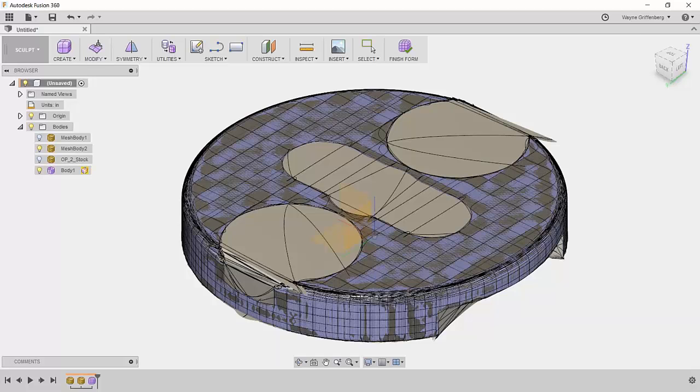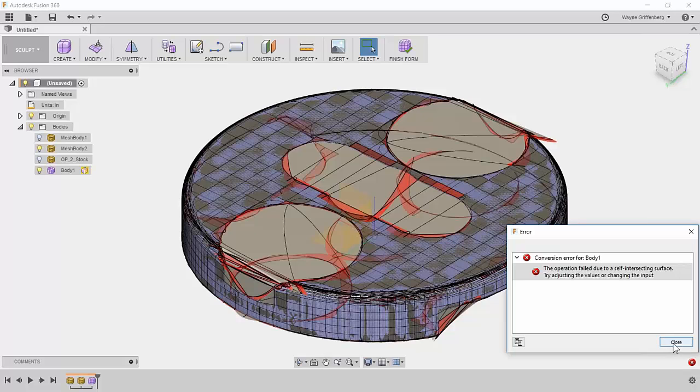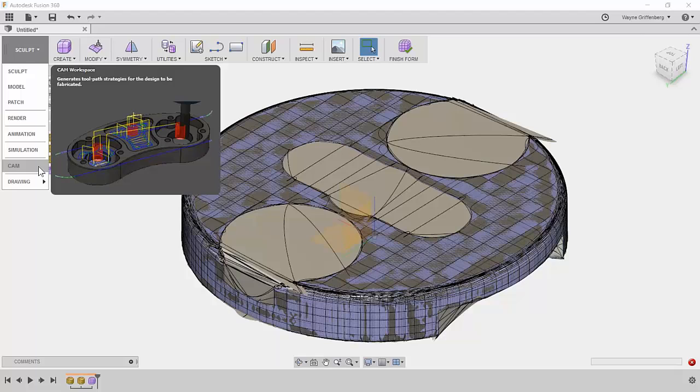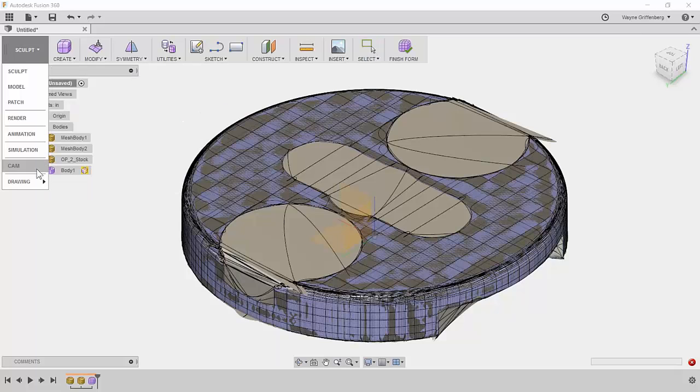I also wanted to draw attention, Wayne, if you can go back to CAM, I don't know how many people picked up on it, but a great workflow you used in machining the backside of your part, where he copied and pasted his setup and then just made a couple very small changes to toolpath the whole backside of the part. If you're not doing things like that and reusing the knowledge you've already put into programming, you definitely should be. And it was nice to see you do that and use a real-world toolpathing technique, even though you're focused on mesh.